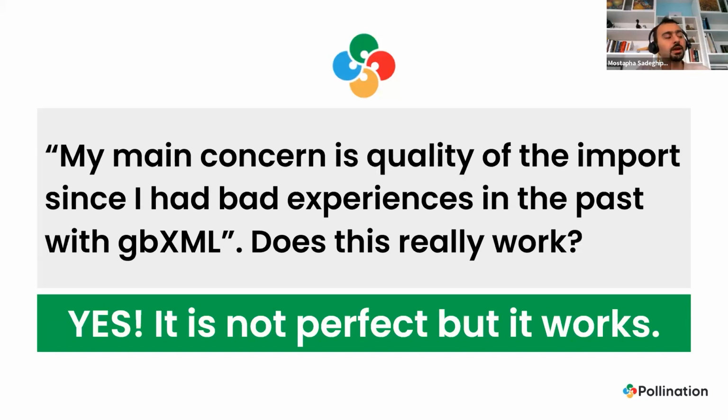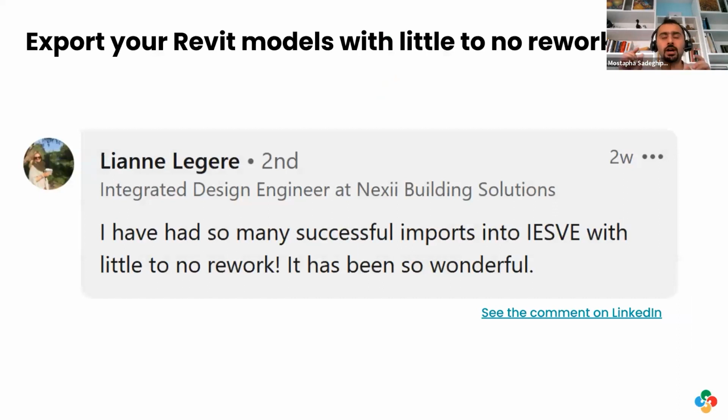We're committed to geometry. Yes, in theory, if you have an open geometry with a little bit of opening, in energy modeling that can be fine. Not every room needs to be fully 100% closed. But if you start there, you introduce tens of other errors that you don't even know about. The normal of the face will be wrong. How big of a gap is fine? We're trying to draw the line in the sand and say you need a valid model if you want to trust what you do, right? We are in 2023, for God's sake, let's fix this. So we are trying to push that.